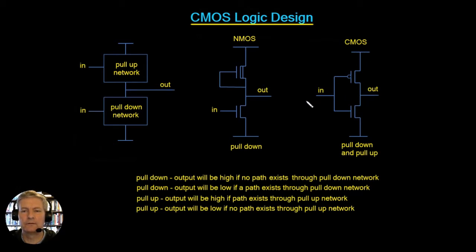device. If we talk through these NMOS inverters, whenever the input goes high, this device here is turned on. When the device is turned on, there's a direct connection from here to ground, so this is pulled low. Whenever the input goes low, this device is off, and this device is always on. So there's a connection from here up to the power supply rail, which means that this point here goes high. So that's how our inverter works for the NMOS.